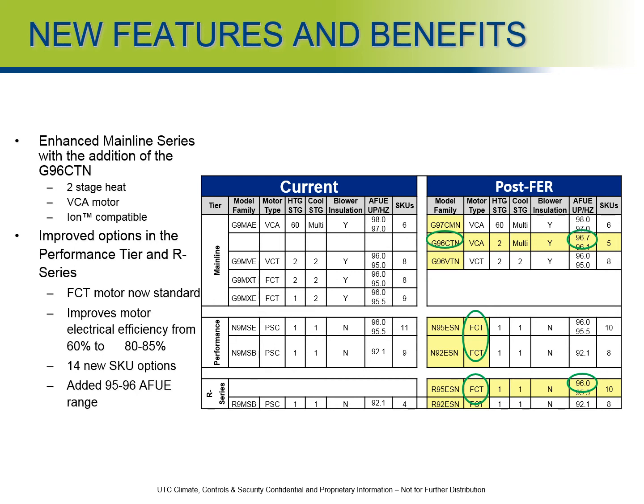So that X13 motor is going to have essentially the same capabilities as the variable constant torque. It's just not going to have as much of a speed range and as many speeds associated with the motor. Typically that motor has a 5-speed tap selection connection on the motor. So you're going to be limited to 5 speeds on this motor. It still has the same efficiency as the variable constant torque and the variable constant airflow motor, but you're going to be limited to 5 pre-programmed speeds in the motor.